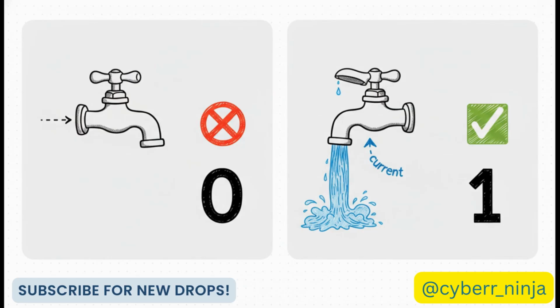In the cutoff region, you apply zero current to the base. And just like that, bam, no current can flow through the collector. The faucet is completely shut. That's your digital zero. Then in the saturation region, you hit it with maximum base current, and the faucet is thrown wide open. Maximum current flows. That is your digital 1. Off and on. 0 and 1. This right here, this is the fundamental basis of all digital computing.